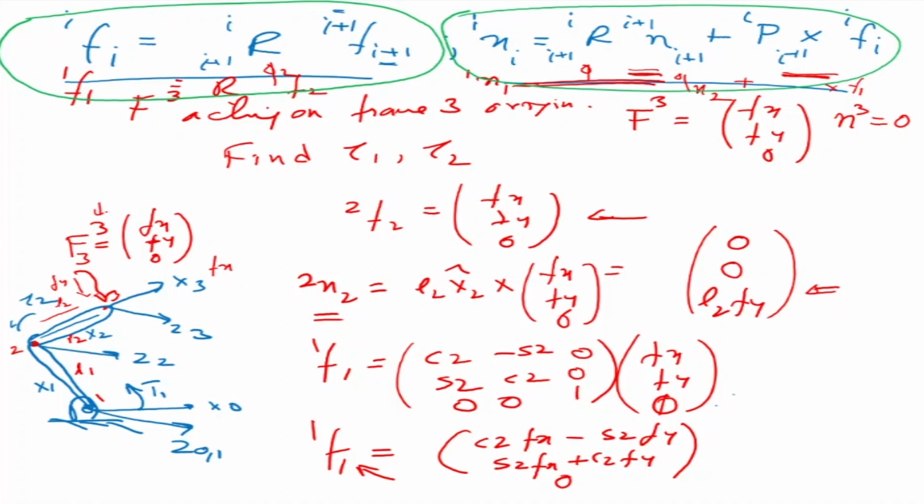Now, the joint velocity will start going towards infinity. Singularities are points where the joint velocity goes to infinity. So wherever the joint velocity goes to infinity, obviously you cannot go there, and also you cannot go anywhere near there. If you want to minimize the energy requirement, we have seen that you have to maximize the determinant of the Jacobian.